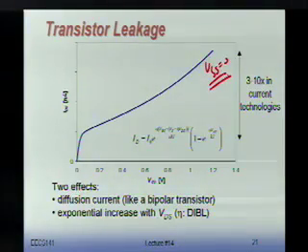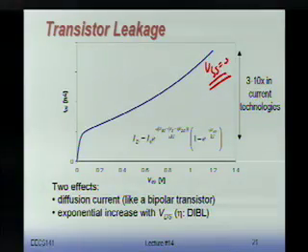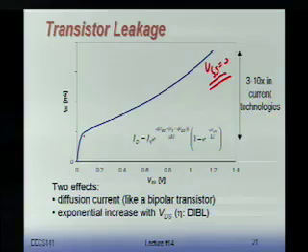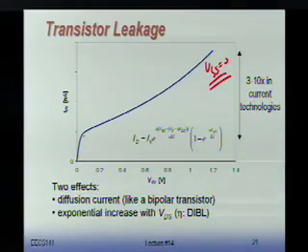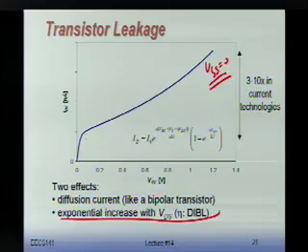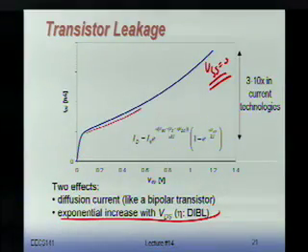Okay? Now, this almost looks like a normal current curve, right? You have your current in the linear mode, and then when VDS goes higher, you have kind of a saturation. And yes, there is some effect like diffusion current, and some effects like channel length modulation going on. But look at this, this is my leakage current, and it says that my leakage current actually goes up substantially.